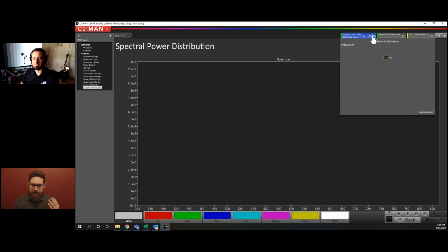So if you're in America and you're feeding it 60, 24, or 30, then you're in 120 mode. If you're in Europe and you're feeding it 25 or 50, then it will be in 100 hertz mode. So I pretty much know we're feeding at 23.98 or 60, so I'm going to just enter 120, and that will set the frequency. Or you can do this initialize, and it will try to detect the frequency.